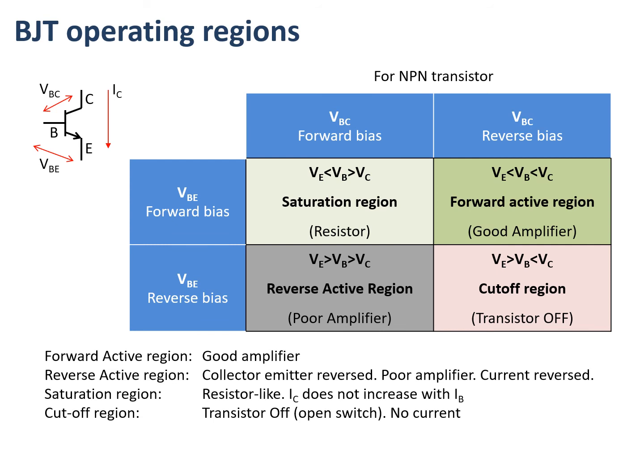So as I said, generally I want to be in the forward active region where the device current is well controlled by the base. I can control the base current very easily by the circuit. That then gives me very good control over the transistor, and that's generally the region that I'll operate the device in for most of my analog circuits.